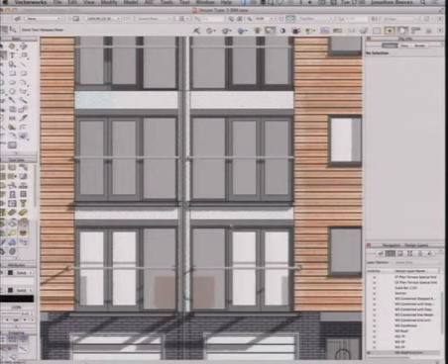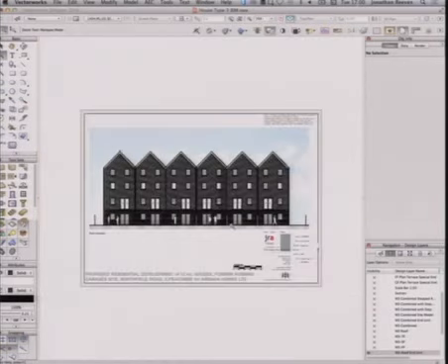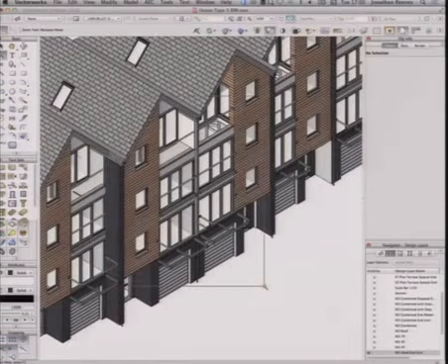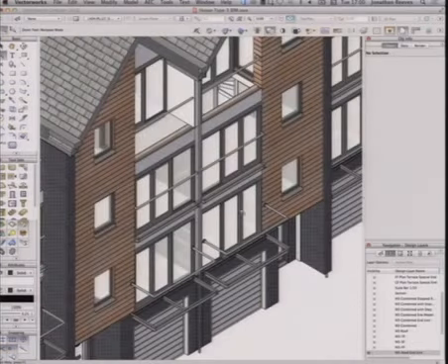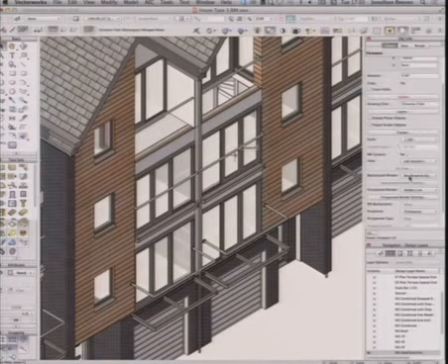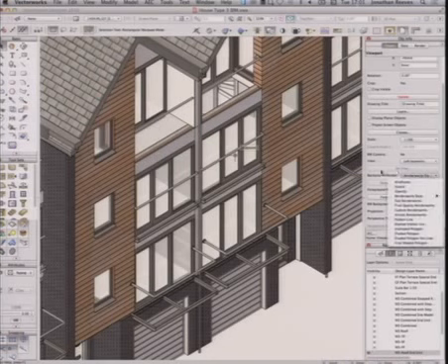Hopefully they look good on screen, maybe not as good as on my screen, but so I'm scrolling through. How do they look? Quite a nice method of presenting. You've got a quite accurate rendered view with a bit of hidden line on top. That's one that I quite like. So to do that, I've used a Renderworks style. On top of that, I've got hidden line.